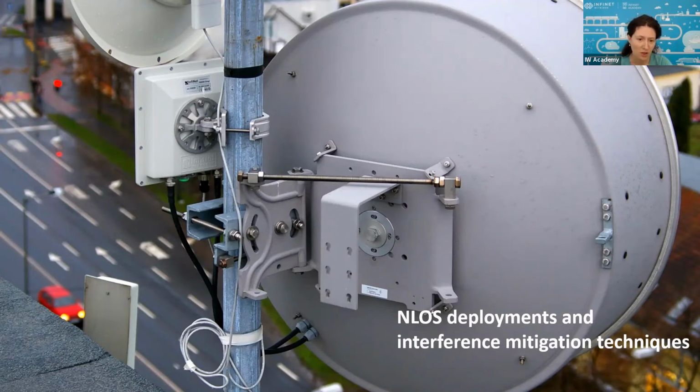I see our first question is that someone tested Quanta 5 in clear line of sight, but it couldn't get a full bar signal. You must understand that clear line of sight is not the only condition to obtain a full signal. You must take into account if you have interferences, for example, because you can have a short distance link with line of sight, but interferences can damage the link. Also, if you have a long distance link, even if you have clear line of sight, you will not have a full signal, for example, because the distance is too long.